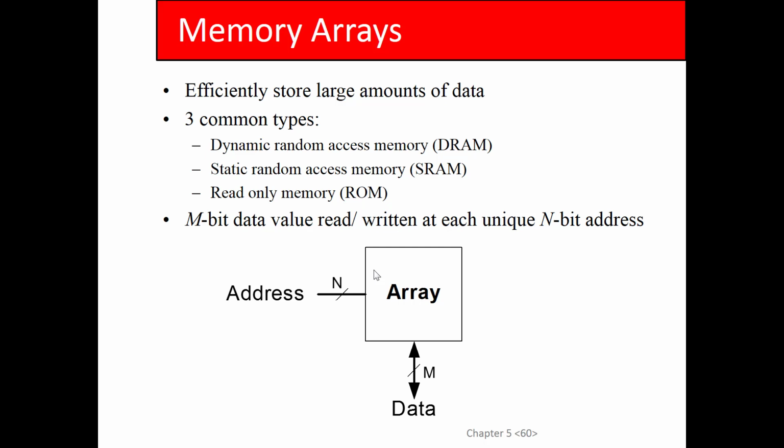In there. There's different types of memory. So when I'm talking about memory arrays here, I'm being very general about it, because you might be thinking, well, memory, you're talking about like RAM, like computer main memory, like you upgrade the memory in your computer and you put in the DIMMs, right? But there's all types. There's DRAM, which is like main system memory, SRAM, which is generally the on-chip memory on a processor.